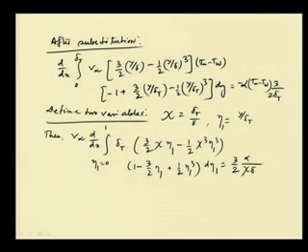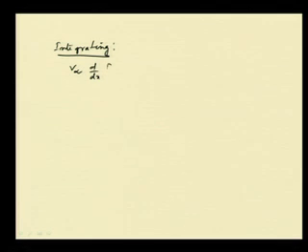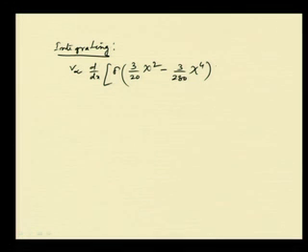Now, we will replace delta T by delta and put it in the form of xi, then we will get, integrating, if we do the integration, we will get that V infinity into d dx of delta into 3 by 20 xi square minus 3 by 280 xi to the power 4, this equals to 3 into alpha by 2 xi into delta.